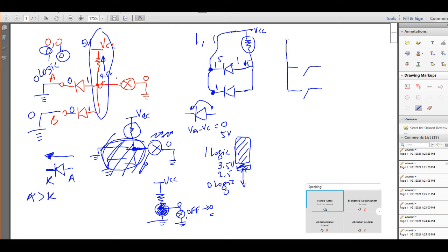Even if this side is connected to VCC and the other side through a resistor, and here the Y, which is the anode, the LED, this is all the time 0. So this is an open circuit. So what we'll see is 4.5 volts on this side. 4.5 volts minus 0 will be 4.5, which means this should be on. Is that clear? Yes. Okay.